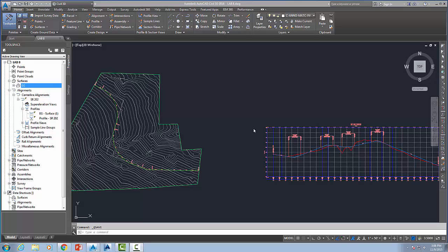and the assembly uses what's called an assembly baseline, and we will attach to that different features that we want to build into this. Now if you were doing this from scratch, you'd obviously have typical sections that you're following guidelines, or building your own possibly, but usually you'd be following some kind of DOT standard. And Civil 3D has a lot of things in there that are similar to that, but they can be modified.